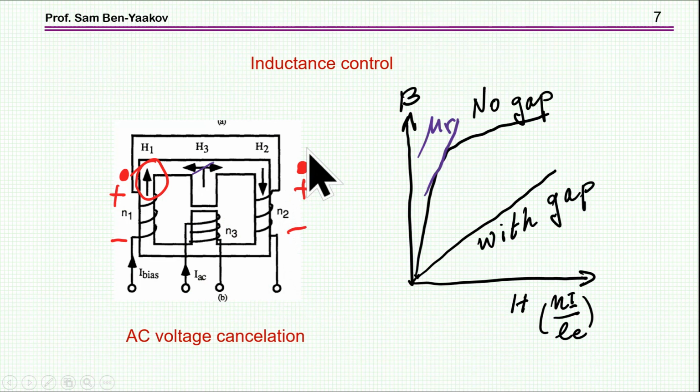So the idea behind this variable inductor is as follows. We have an inductor built around this double E-core with a gap. Now the flux of the AC is passing through here and here, while we have then a DC winding here and here. It's a continuous winding, but it goes in this direction, so therefore there is no interaction between the AC and the DC windings, and furthermore, by having two windings and the polarity of the imposed AC as shown here, they are actually being subtracted. So as you look here at the DC bias terminal, ideally you will not see any AC. Of course, due to some mismatch you can have some, but most of the AC is subtracted.